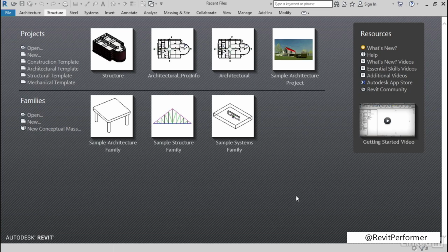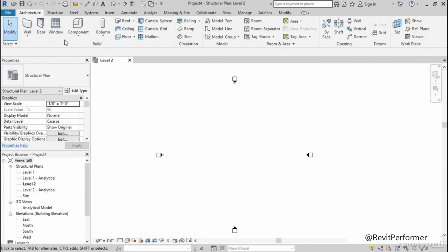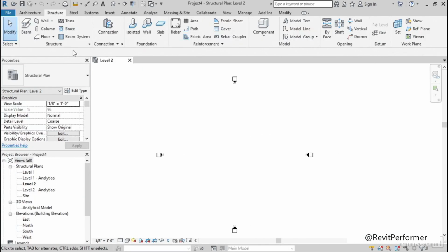Revit will want you to pick the host of the reinforcing, then the start, and then the end of the direction in which the rebar will be spaced. Then we need to play around with the embedment. Jumping to Revit, let's start a project using the structural template. On the Structure tab, let's click slab.